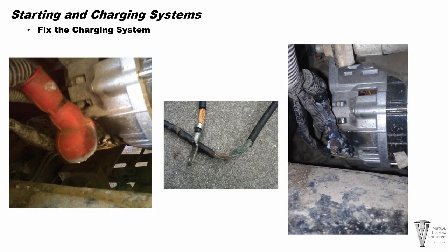If you have any damage to the charging system, you must fix these first. Charging system problems, especially overcharging, can cause havoc with the entire electrical system. It's not uncommon for an overcharge condition to force an onboard computer to default or go into a limp mode. The result can be some very unusual symptoms and erroneous trouble codes.